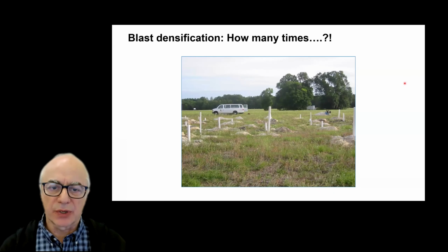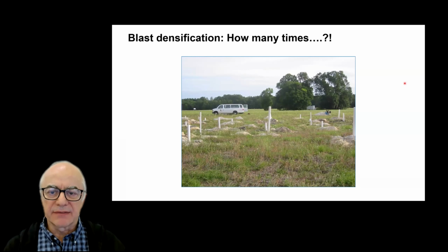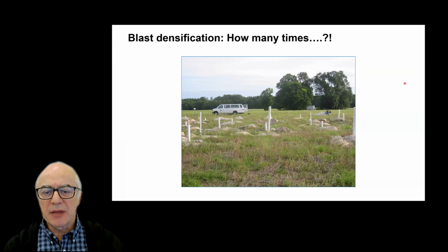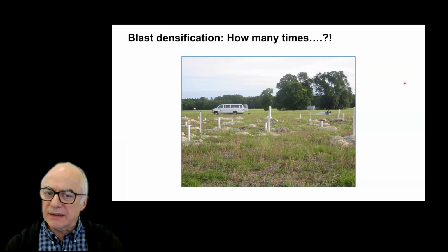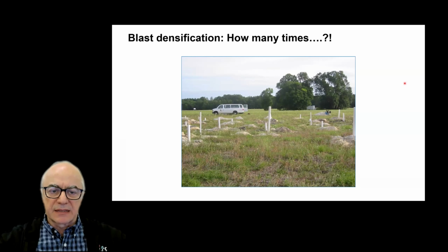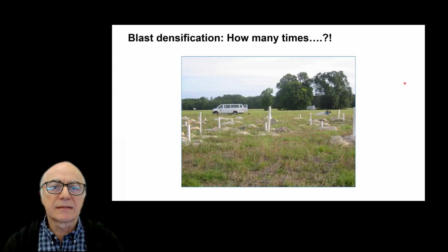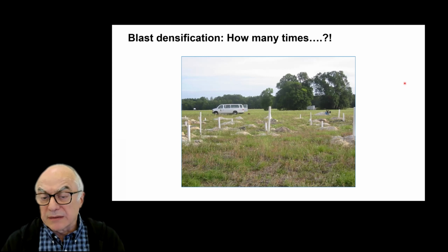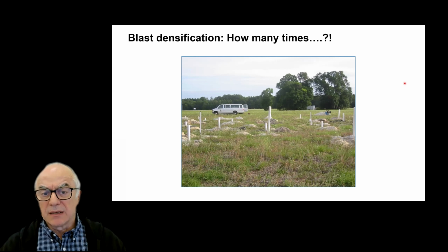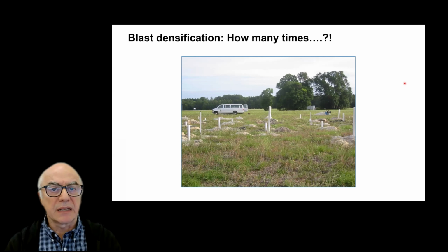Consider the following situation. There is a densifiable layer, in fact, a fairly loose sandy stratum, which may be somewhere between 10 and 15 meters of depth, so that it is very difficult to change the properties of that layer in a very extensive plateau or valley like the one that you see here, using techniques such as deep dynamic compaction. So one may wonder whether blasting that layer will eventually increase its density to values that will prevent liquefaction.